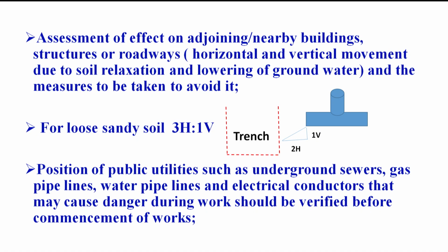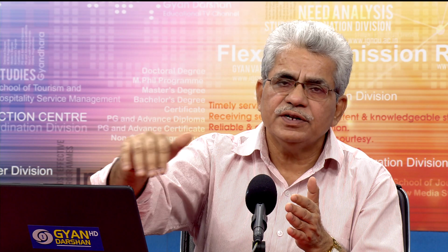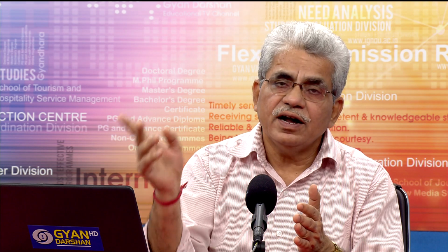Then, assessment of effect on adjacent or nearby buildings. This is also very important, because you are doing excavation in your property, but if you are excavating more than the depth of the foundation of the adjoining structure, then the excavation in your property will affect the adjoining structure basically. So we have to see how the adjoining structure or building is going to be affected when we are doing excavation in our own property.